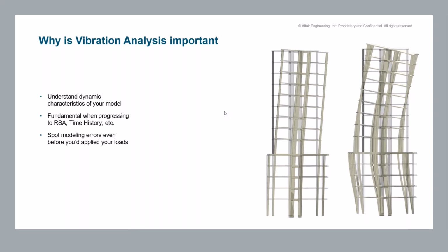Why do we want to run a vibration analysis? This is a pretty loaded question, but I've tried to lay it out in a few different points here. I think the most important aspect is that we want to run some sort of dynamic analysis beyond just understanding our mode shapes and so on. Understanding the dynamic characteristics of your model is a really good first step. And when I say dynamic characteristics, I mean things like the mode shapes, the natural frequencies, period of vibration, and so on, mass participation. This is all very important information if you want to run a time history analysis, a response spectrum analysis, for seismic loads or some sort of other type of time varying load that might occur.